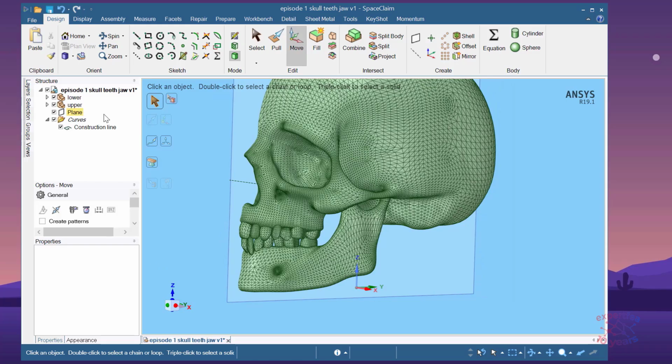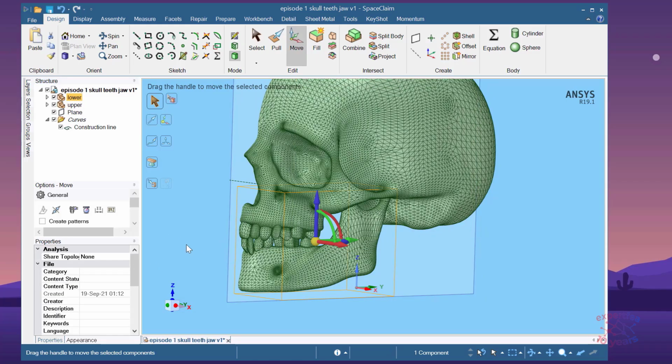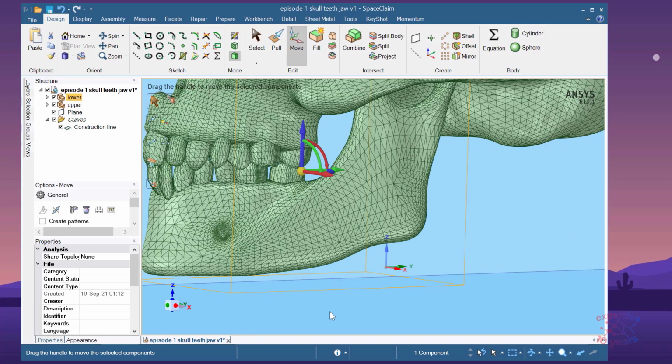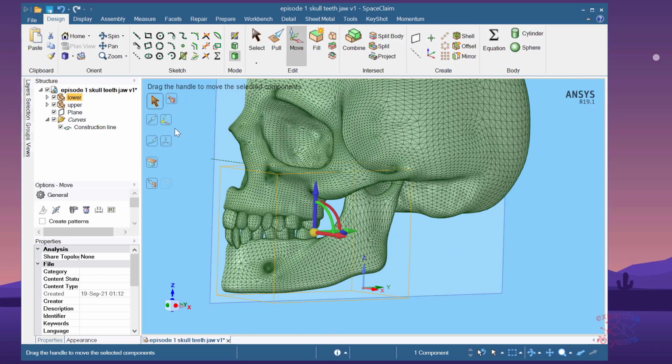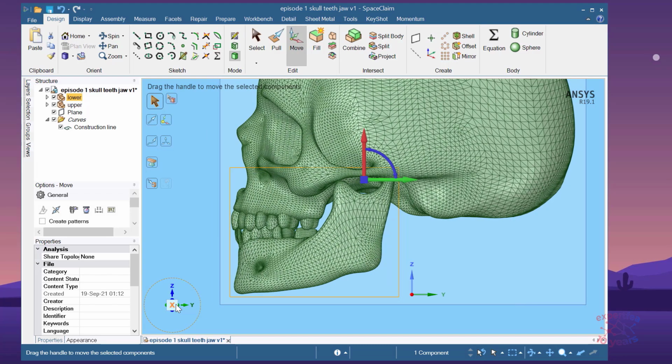Alright, so let's move this assembly. Yes, I selected it. Let's press the anchor button. Then as a reference, we will select the construction line that we just moved. You can see now, it's not easily visible, but we'll make it a normal, planar view.